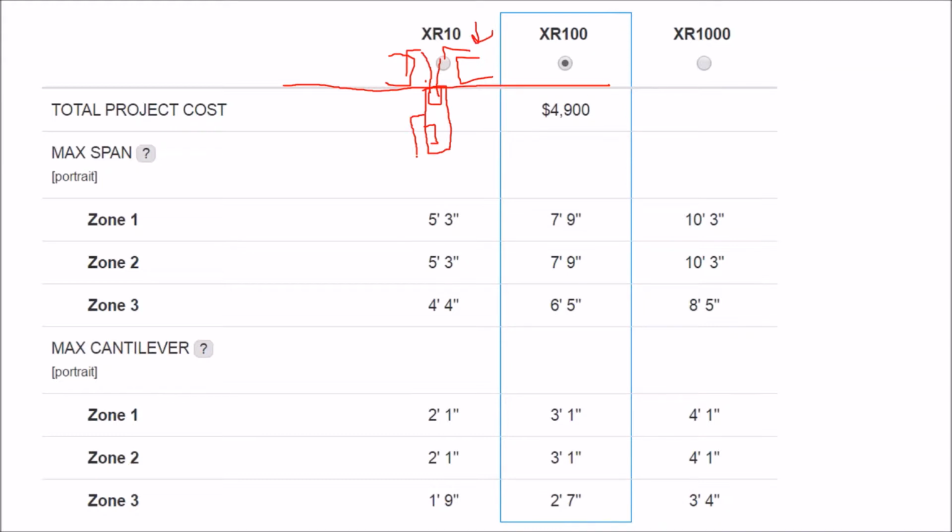And then you have an attachment point called an L foot, and the bolt goes into this channel, and then your lag screw goes through the L foot into the rafter. And more of your top quality L foots nowadays might have 2 lag screws to prevent this L foot from trying to torque up, which is common in heavy snow loads, where you get a lot of weight going down. You might have the L foot actually trying to torque the other direction.